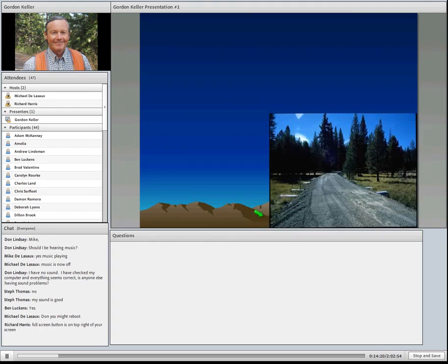Here you can see, now I don't know why it's only showing one of the two photos here, a photo of a typical crossing of one of these meadow areas where it's been put in with a drained, permeable rock fill and a bank of culverts. And like I said, it's a fairly expensive treatment, but it's making up for being in a spot where you probably really shouldn't be in the first place. So it's a relatively expensive environmental measure.